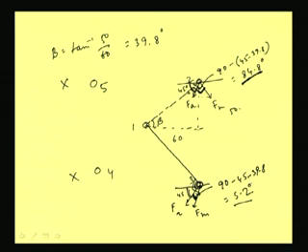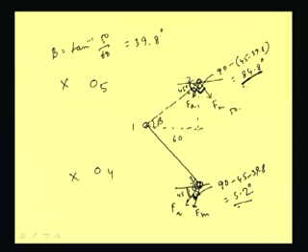From this we can easily tell that the angle between these two is less compared to rivet 2. So, rivet 3 is the most affected rivet. If we take the value of rivet 3, then we will be able to find the safe value of the joint, because in rivet 2 the angle is 84.8 degree and in rivet 3 the angle is 5.2.